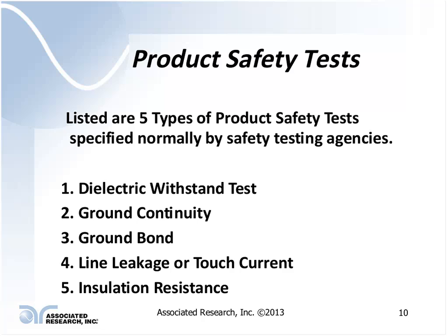Number 4, line leakage or touch current test. This is a test that is done on the product to measure the potential shock hazard that product could have to an operator or an individual that is touching the product under certain normal and fault conditions. Okay.